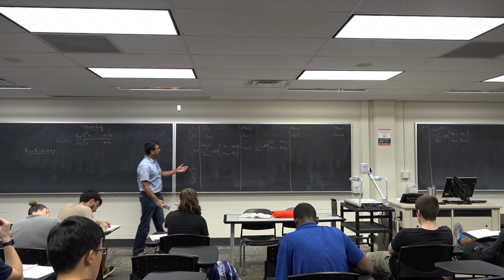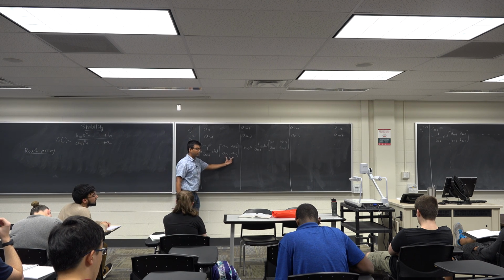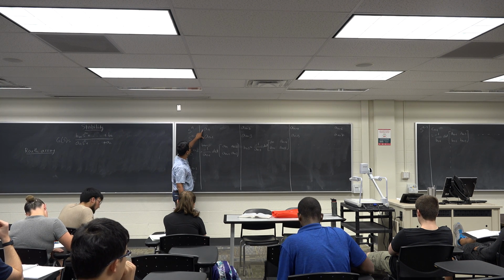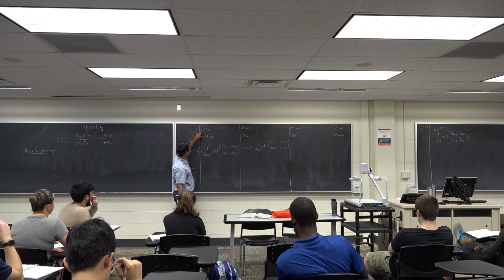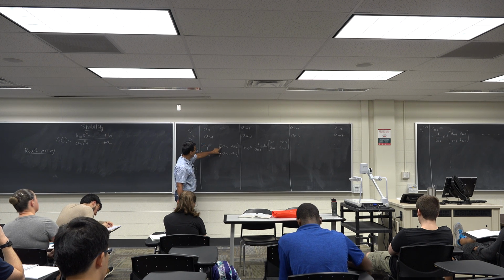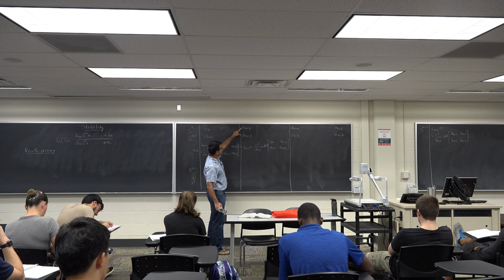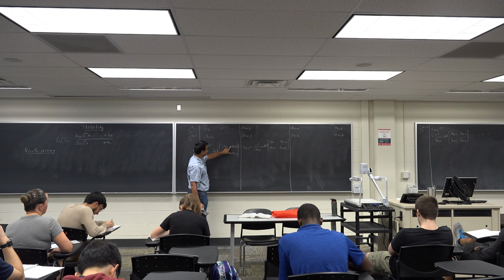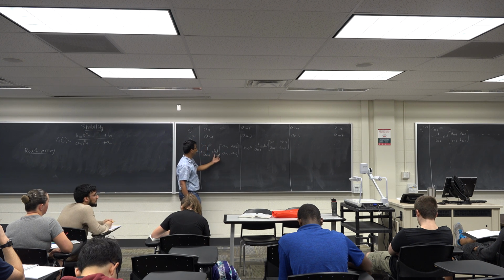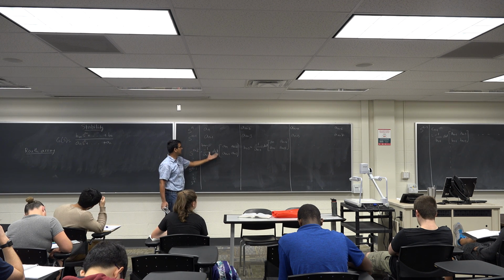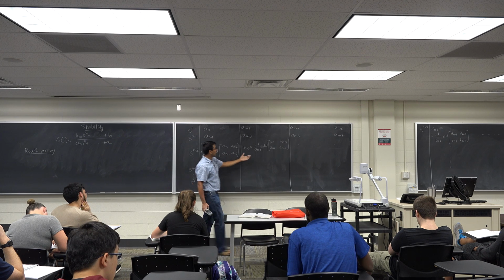So how did I construct this Routh array? I created a matrix. I'm at Sn minus 2. I created a matrix which consists of the first two numbers of the first column, an and an minus 1, and then the subsequent column, the last two numbers, an minus 2 and an minus 3. I take the determinant, divide it by minus 1 over this quantity an minus 1, and that gives me this number Bn minus 1.